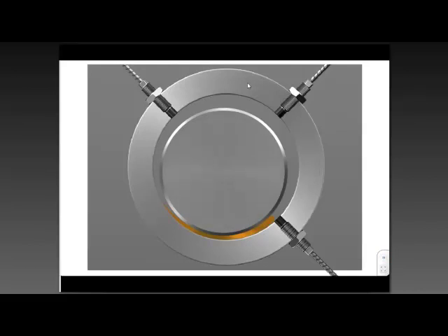So instead, we use these probes called proximity probes or non-contact eddy current probes. What's actually happening is this is measuring the distance, or is sensitive to the distance, between the tip of the probe and the shaft. We use triangulation, so we use two of them mounted 90 degrees apart. And we use a third sensor because we love to use phase in this application, and this would be mounted somewhere else along the shaft looking at a keyway or something like that. So this is called the key phaser. Bottom line is that using this information we can tell exactly what's going on.